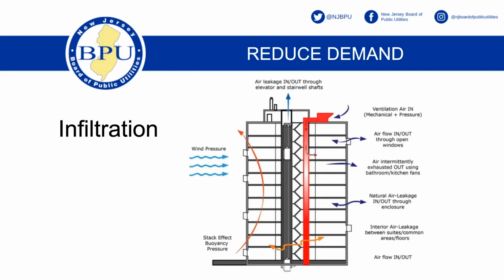The stack effect is really a force that moves air upward. And having a certain amount of elevation, even how many stories on this building? Maybe 10 or 12? It's a fair sized building. Most of you are in buildings that are, you said yours, Christopher, was 12, 13. A lot of you are in tall buildings, and it creates this buoyancy of the air that moves air from way down in the basement all the way up to the top, and in some cases out the roof.